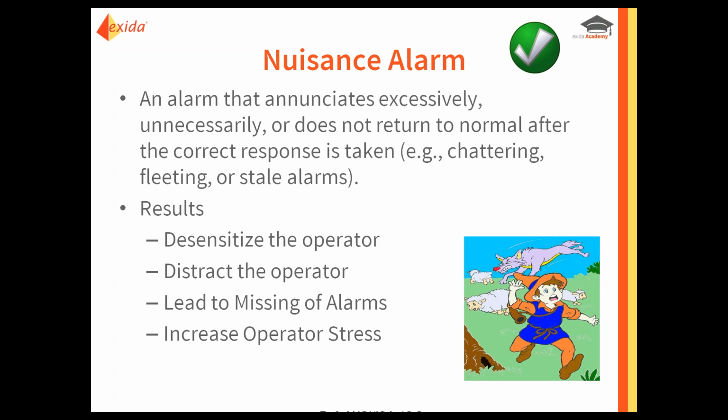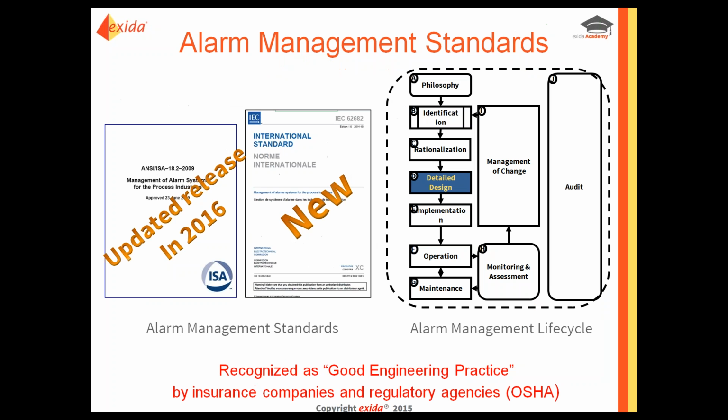Now, that can become very dangerous if there becomes a culture of ignoring alarms, particularly if in a certain case, maybe the alarm that's been ignorable for months is now all of a sudden important and the operator has been conditioned to ignore it. So eliminating nuisance alarms so that operators don't develop that conditioning to ignore alarms is really important. And that's what we're going to talk about in Technical Report 3.